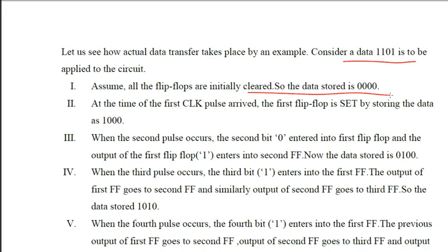Now on the next clock pulse, we input the value corresponding to the least significant bit, that is this one. This LSB is shifted in, which means the data stored will be 1000.